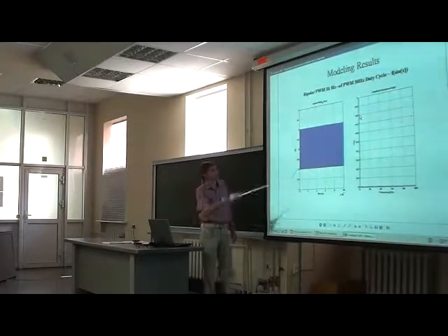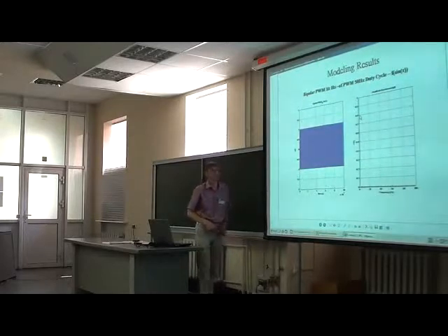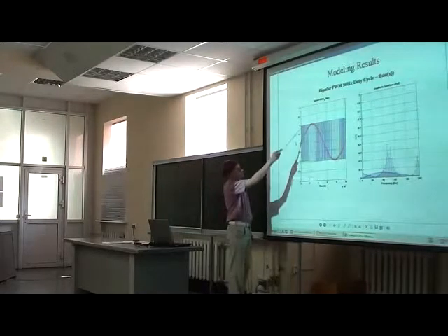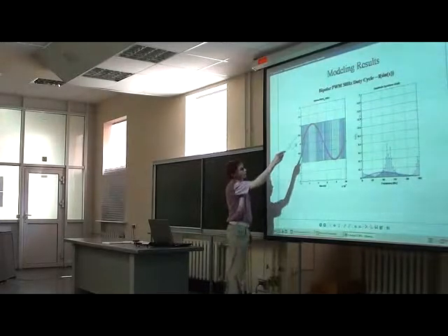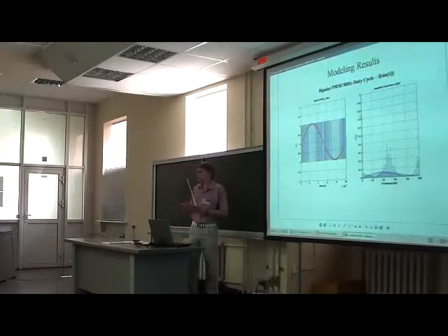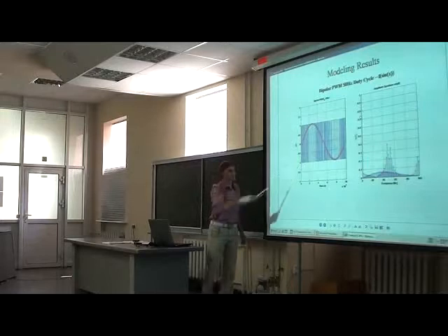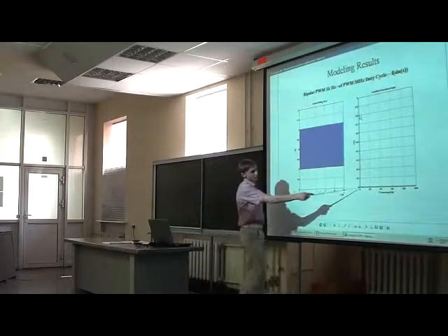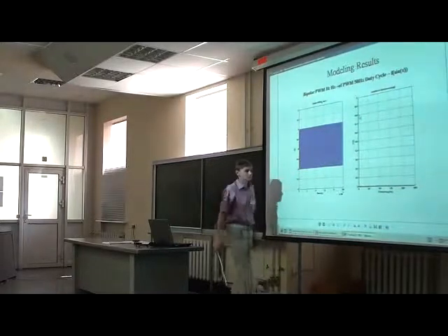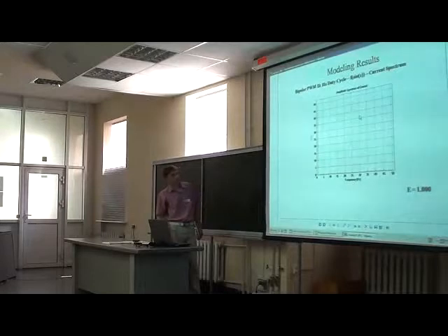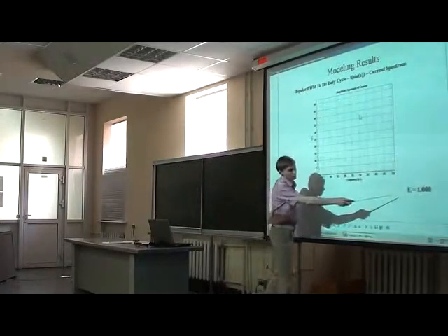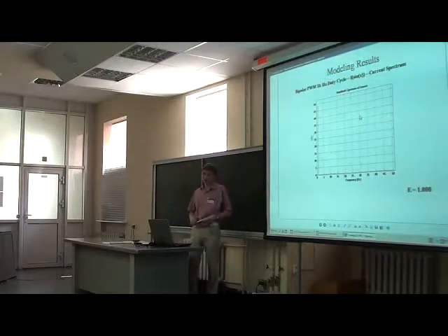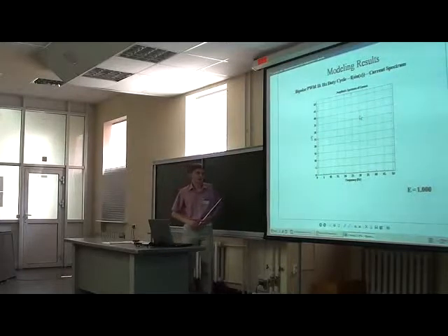And now I can show you that we increase the PWM frequency to 1 kilohertz. Each pulse from this figure, we generate as 1 kilohertz pulses. And we get this figure. You can see here that we have only one harmonic, and the energy efficiency here is 1. By increasing the PWM frequencies, we get a better result, but